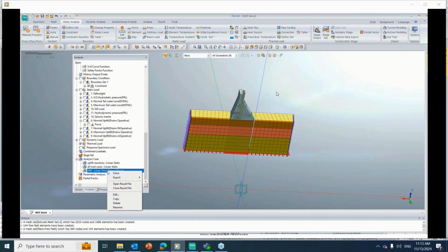Okay, so when that was applied, the structure was becoming quite heavy, quite big. The sections were coming out quite big for any structure, whether it is a building structure or a dam structure or anything. So then they decided, let us reduce this acceleration to half. They reduced that peak ground acceleration to half, Z by 2, then multiplied it with the response of the structure based on its time period. With that coefficient, they multiplied the mass and applied that force to get the reactions.